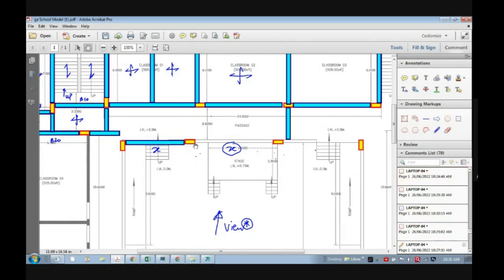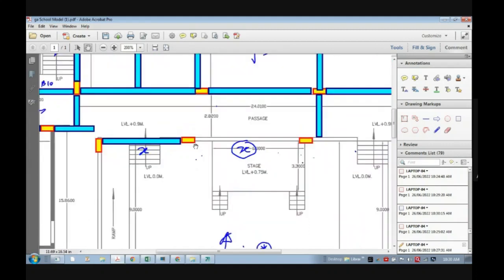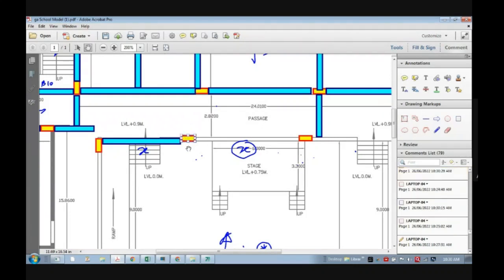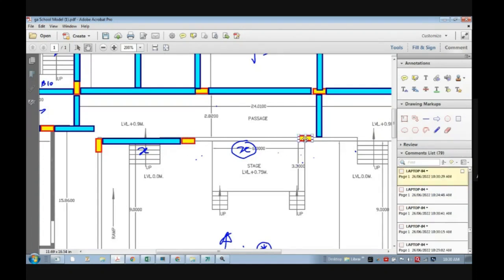Now let's put these columns, sorry, beams here. Now for the offset, you can take a decision, either put the offset inside the passage. Generally, inside the passage, offsets should not be there. We should avoid that. But if the architect is happy with inside offset or outside offset, you need to ask. If he is using the offset of columns as an aesthetic part, then you can take it outside. Okay. So many times columns are also exposed, and the offset is used for aesthetic purposes.